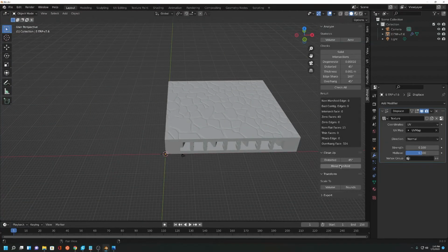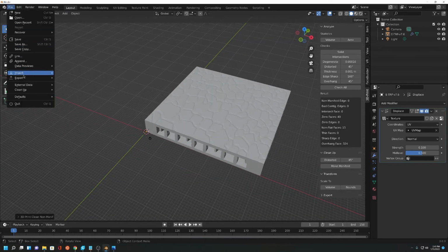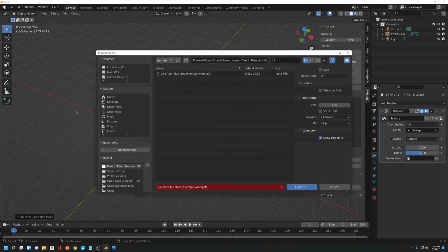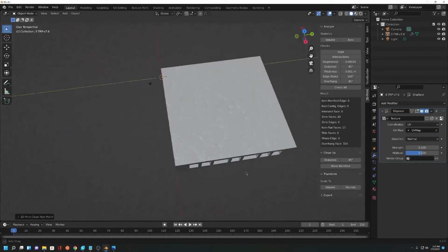Okay, so you saw that pop on the bottom. Last thing we do is hit Make Manifold. There we go. Click it. Again, this might take a little bit. And boom, did it. It said negative 29 edges, negative 29 faces. Didn't fix any vertices though. All right, so File, Export, STL. Do it over the same one, save it. So now we actually have a manifolded foil just fine.